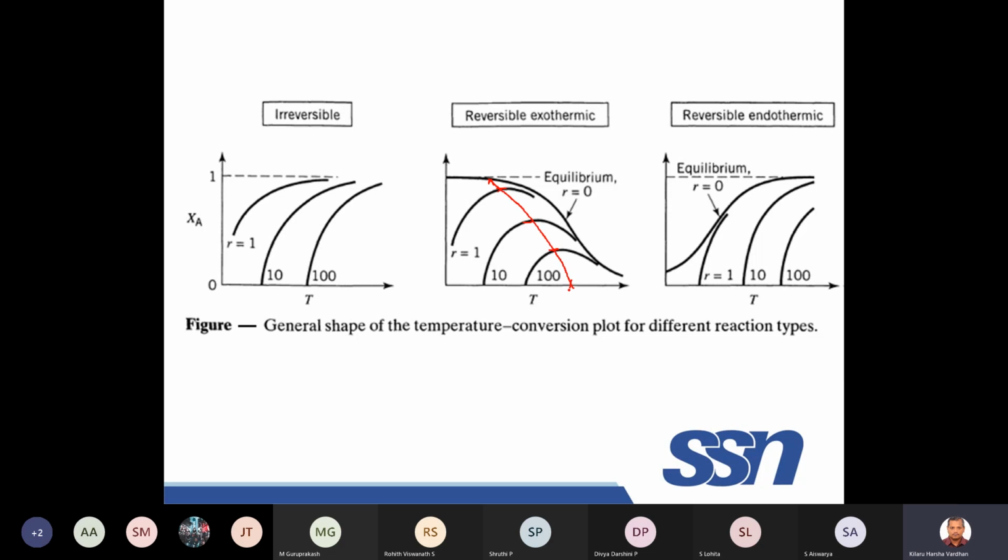You see here the temperature is high; if you go up along the locus of the points, here the temperature is less, here it is less. So you should go on decreasing the temperature in such a way that you get the maximum rate and maximum conversion. That is why in exothermic processes, we decrease the temperature by inserting some cooling coils or taking out the products and again sending them in, right?